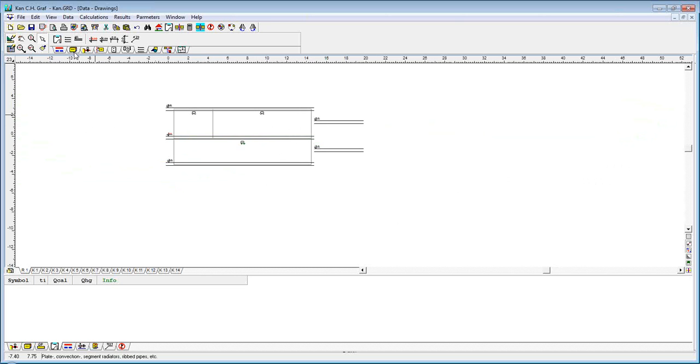And now let's choose the radiators. So I choose the radiator tab, and in this first system, which will be very, very simple, as I also recommend to you: if you start to learn the program, please start with a pretty simple system. Learn how to design a very simple, very small system, and that will be easier before going to the next one, a bigger system, because it may be a little bit tricky to start with a very big and complex system as the first one. So let's say that we would use plate radiators with the side connection.